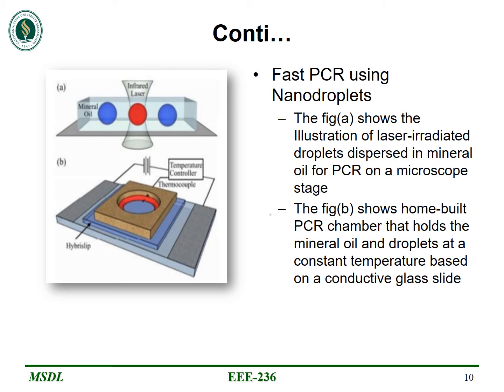Many biochemical assays, however, require more than the fluid circuitry. For example, the polymerase chain reaction, one of the more prevalent biochemical assays, requires temperature cycling. One method commonly used for miniaturized high throughput droplet based PCR chips incorporates a heater or a temperature sensor inside the substrate, as shown in the figure.